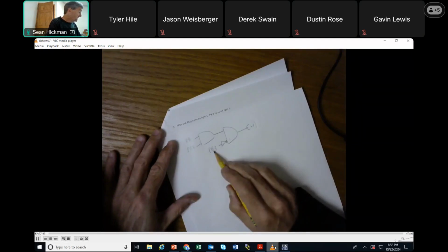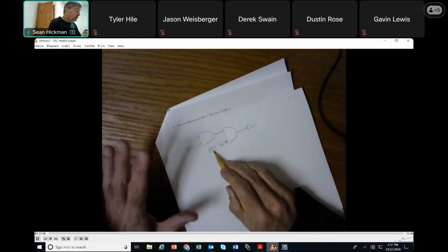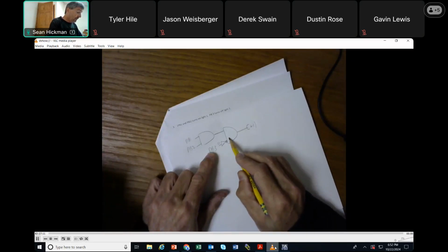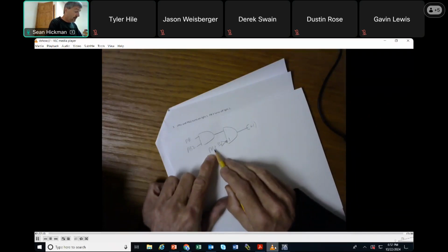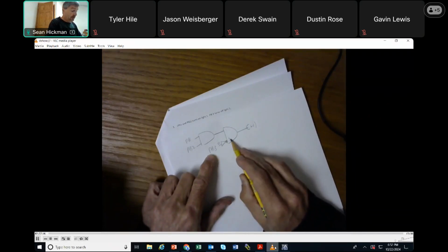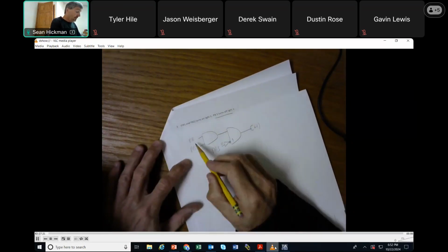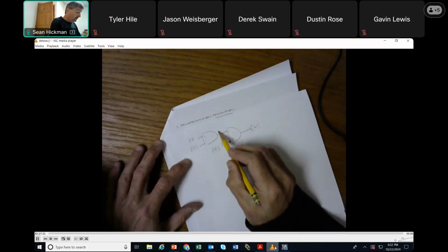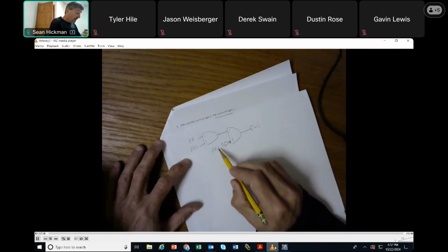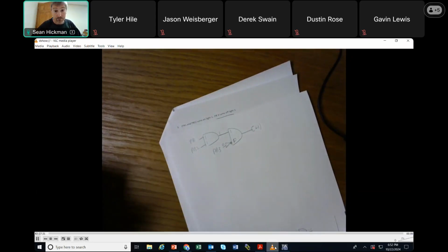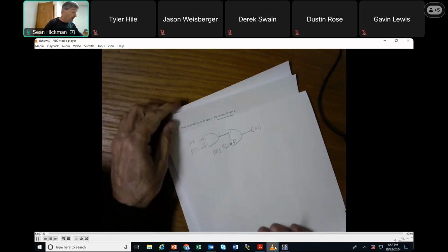So PB3. If I'm not pushing it, I got 0 over here inverted to a 1. So if I push PB3, that 1 becomes a 0. And if this was on, it would be going off. So I got a PB1 and 2, a 1 and a 1 would give me a 1. So 1, 1. Push the button, 0, it goes off. All right, everybody feel all right on a scale of 1 to 10 about the inverted PB here to turn it off? And you start thinking about how that looks for a normally closed button, right?